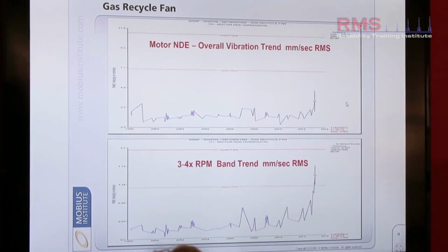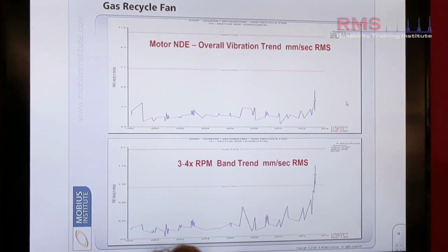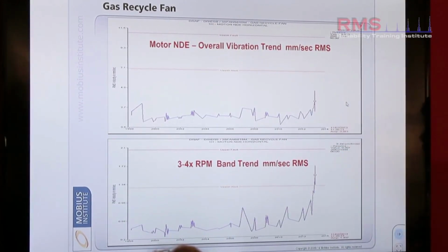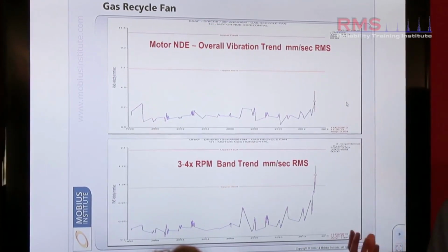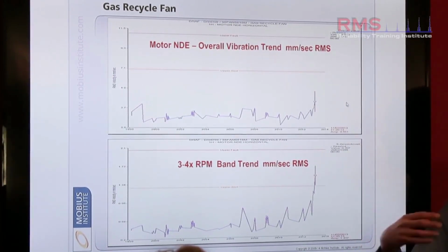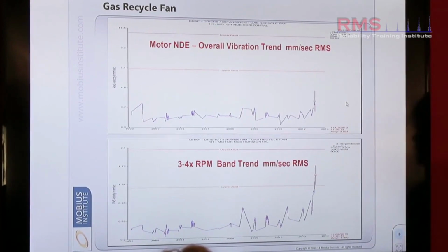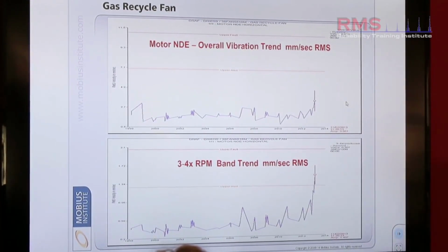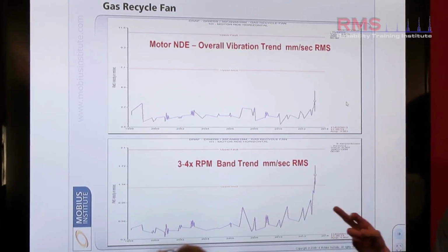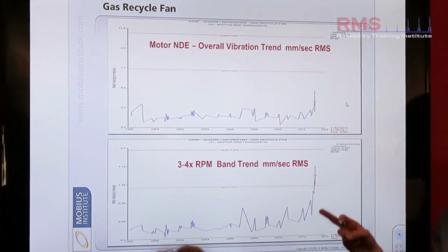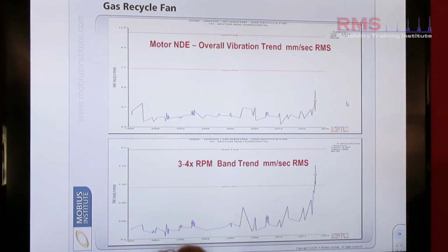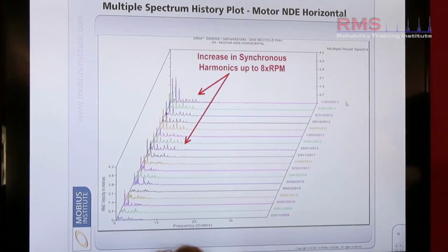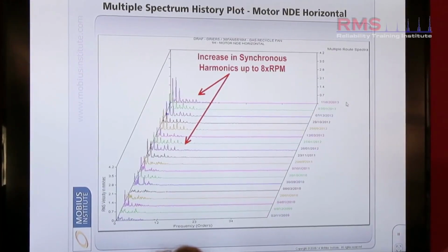So my general vibration trend, according to an ISO standard, actually was well within a tolerance. But because it's important not just to trend the general level of vibration, perhaps different parts of the vibration, i.e. the different heartbeats, you can trend them independently. This particular trend segment here obviously violated an alarm. Drilling down slightly deeper into the data, you can see the degradation.